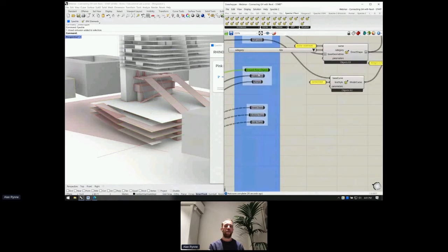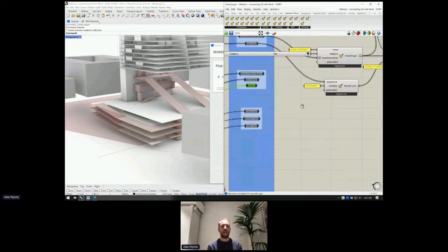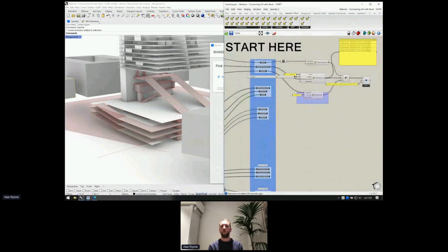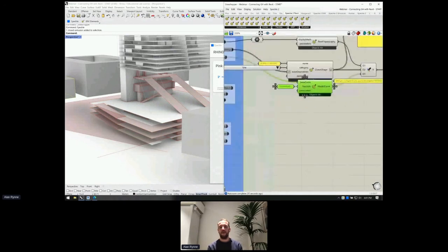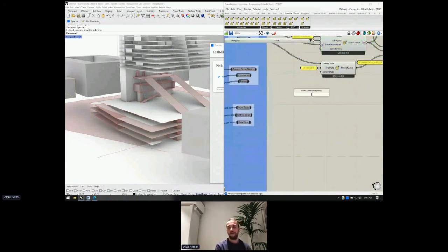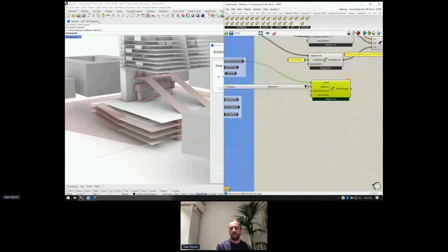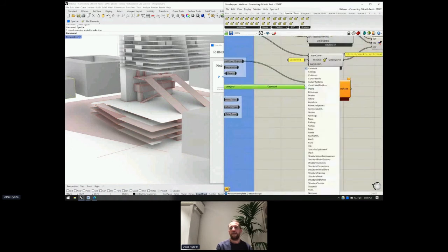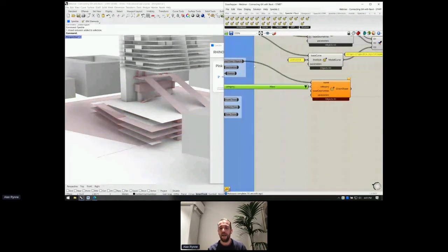If we wanted to send the ground floor objects, the foundations, and the ramps, the easiest way to do it, to just keep things on their schedule, is send them all as direct shapes, but actually specifying each category precisely. So in this case, we would say that my ground floor objects are window stairs, specialty equipment, who knows, and let's call them masses.